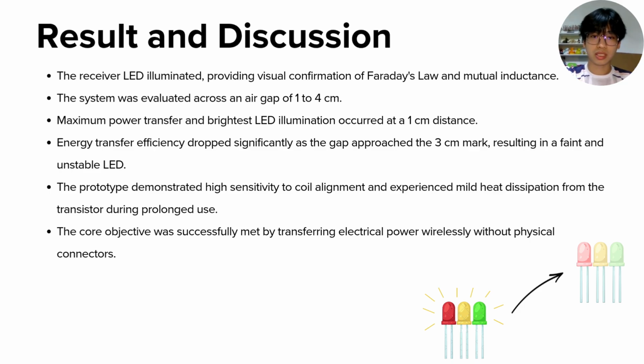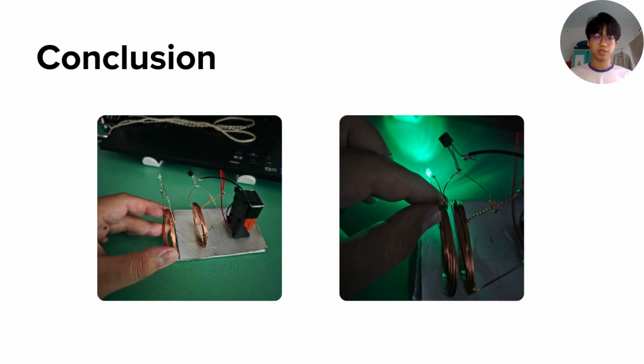We also found that the system is highly sensitive to coil alignment, and the transistor produces mild heat during extended use. But overall, despite these limitations at maximum range, we successfully achieved our main objective, transferring electrical power wirelessly across the physical air gap.